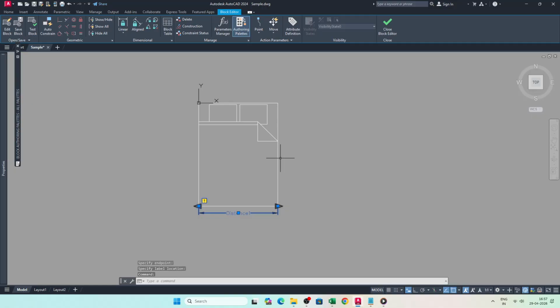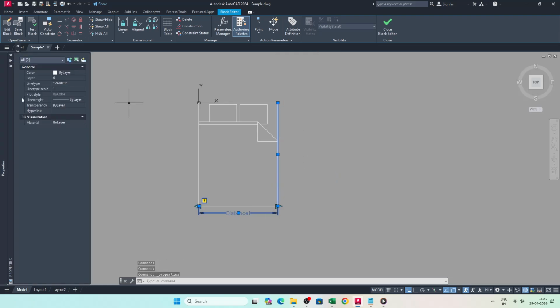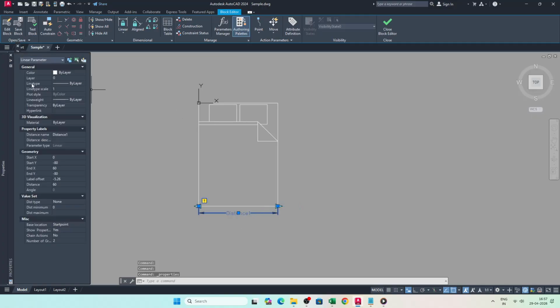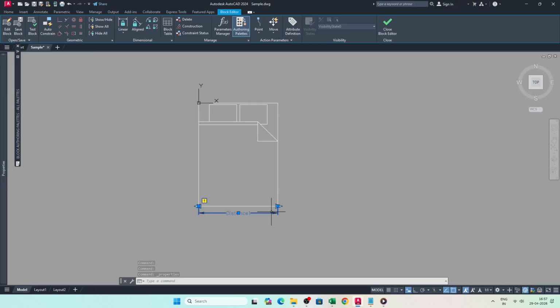With the parameter placed, right-click it. Choose Properties, and set the number of grips to 1, or whatever your design requires. A single grip at the end you intend to drag is common because it makes the behavior obvious. One end stays anchored while the other moves. If you use more than one grip, be clear about which side should do the stretching.